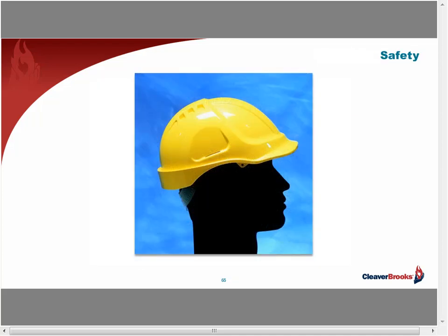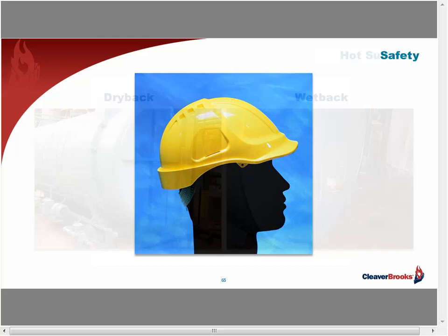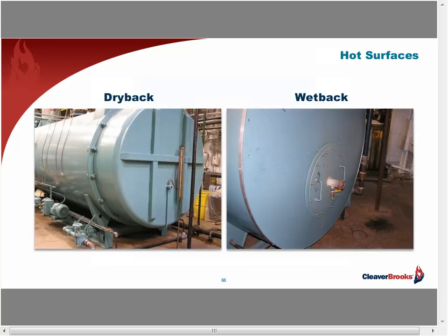All right, enough on possible solutions for reliability impact areas. Now let's turn our attention to the solutions for the major safety impact areas. And we'll start with possible burns caused by direct contact with hot surfaces on the boiler. You'll remember I called your attention to the flange area on this rear door on the left, which gets very hot to the touch, as well as other portions of the door, especially the lower half. The first thought is to insulate the door to prevent personal injury.